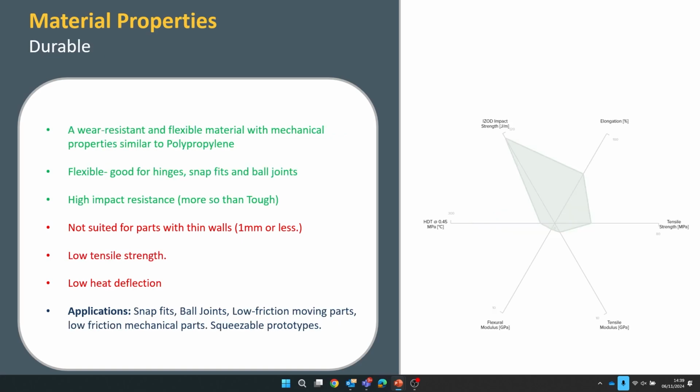And again, there's loads of stuff here. What I would recommend you do if you do decide to buy a 3D printer, or any machine for that matter, look at the materials that they use. Go to the website where they sell those materials, and you'll find something called an MSDS sheet, Material Safety Data Sheet. And it will tell you whether that material is toxic, what you should do in terms of handling it, should you wear specific types of gloves. For instance, for SLA, you need specifically nitrile gloves. You don't need to know this, but worth throwing it out there. If I were to use latex gloves, that material would eat straight through, absorb into my skin, and I'd get toxic quite quick. So you do need to be careful.